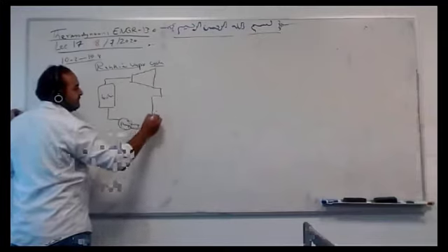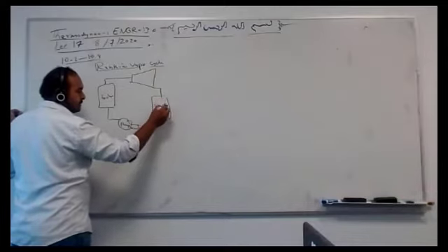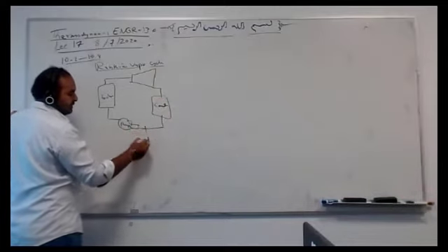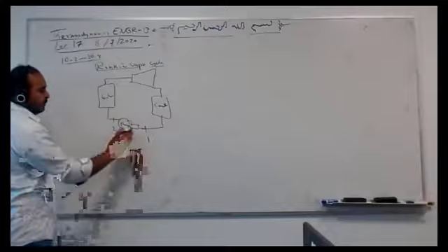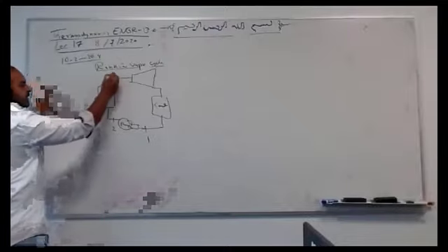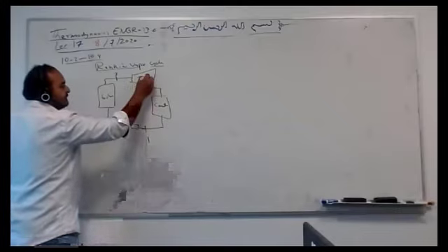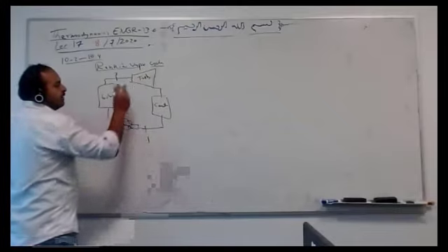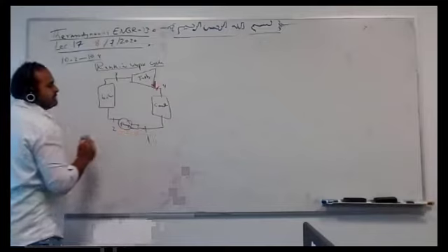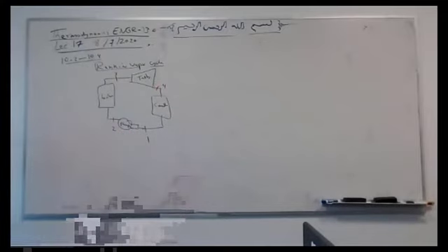Then we have a condenser, then we have a pump. So here 1 to 2, compression. 2 to 3, heat addition, boiler. 3 to 4, turbine expansion, get work from the turbine. 4 to 1, condenser, go back to 1. Exactly the same as the Brayton cycle. This is very identical to the Brayton cycle.